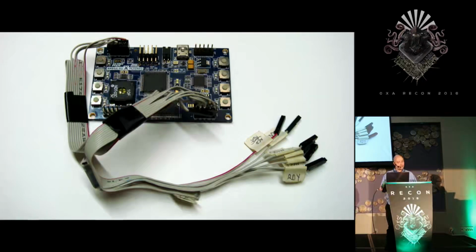At one point, I wrote software for an AVR32 device that has a synchronous serial peripheral that could handle the 27 megabit serial transport stream. My implementation was a little bit ugly, but rather than clean it up, I was able to use it as it was. It was limited to a 64 kilobyte chunk of replay and logging, which was good enough for what I needed to do. What it did show me is that the full transport stream passes through the ACP.